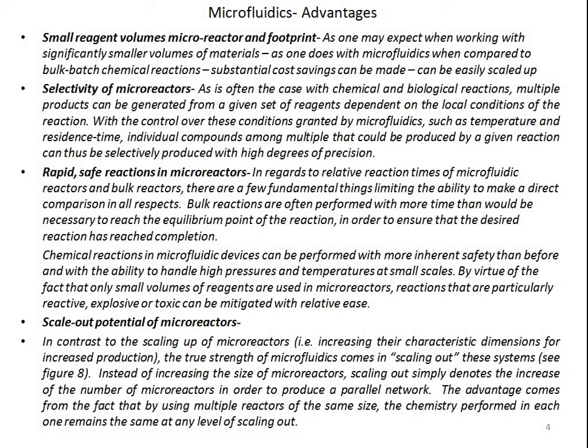Now, scale out potential. What I was meaning to say with this is the scale up potential of microreactors, in contrast to scaling up of microreactors, that is increasing the characteristic dimension for increased production. The true strength of microfluidics comes in scaling out. What does scaling out mean? Instead of increasing the size of microreactors, scaling out simply denotes increasing the number of microreactors in order to produce a parallel network.